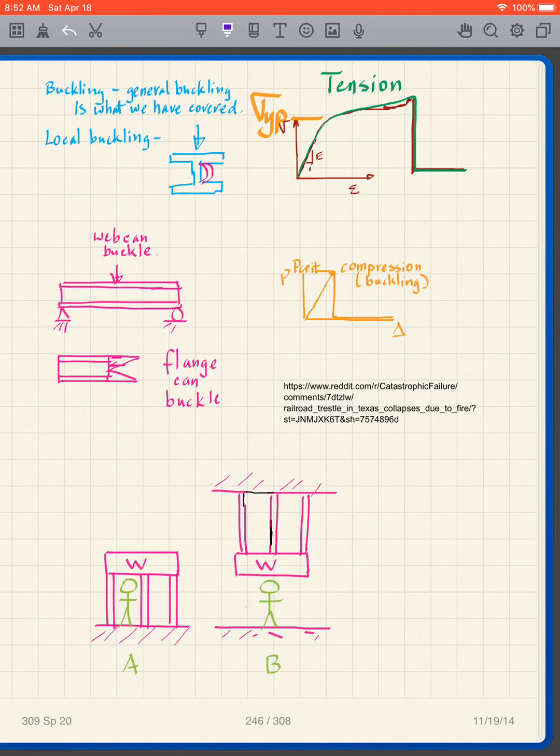In contrast, let's look at this structure where everything is in tension, where these members are all in tension. What happens if this is undersized? Well, if that is undersized, what do we find? That means we're getting yielding here, and I have all this remaining resistance in that member.